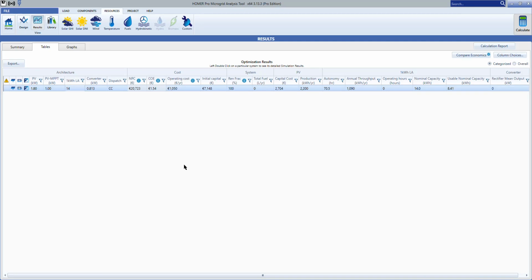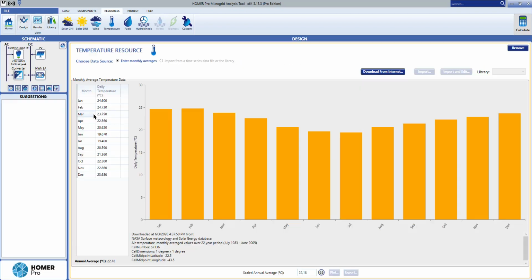Okay, so now for the second part of the exercise, I'm going to change our numbers for the load, only for those lights of 300 watts from 7 p.m. until 11 p.m., and I will substitute them with 40 watts, since we have 5 LED lights of 8 watts each.